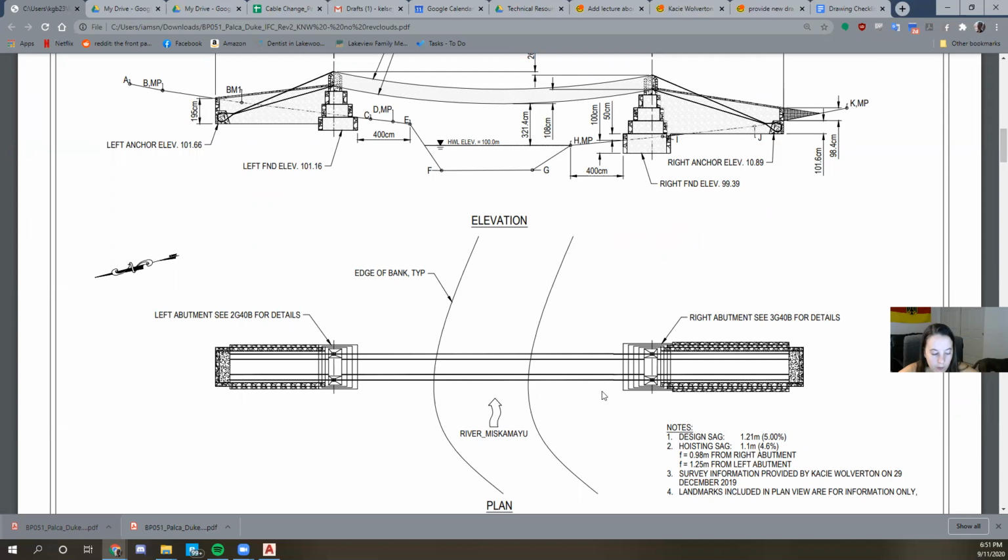As an engineer, you want to make an educated guess on the highest load the bridge could ever see, and that's what we design the cable capacity for, the abutment overturning, the anchor uplift, and sliding. That just goes into your calculations. It doesn't go anywhere here.